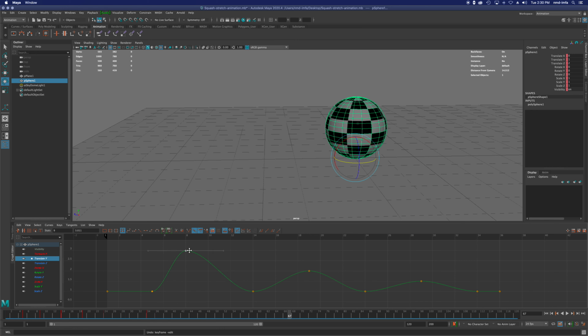Sometimes if you hold Shift, this one it's not really snapping for me right now, but when you have groups of them, you can hold Shift and move them, and they will kind of snap along that same value line. But I can click on each one here, and you see how I actually get the value of it right there. So I can see that's at 1.002 as an X value. That one's at 2.989. So if I wanted to change that, I could type in 3, and that's actually going to bump that up and change the value of the keyframe. I don't have to hit set again on that one. And this one back to 1.